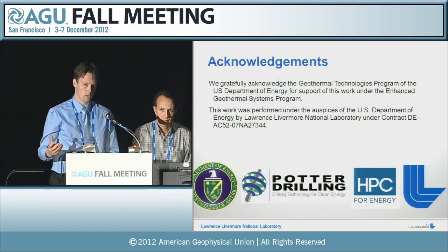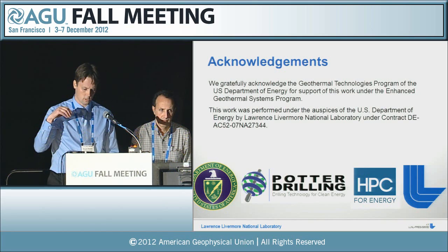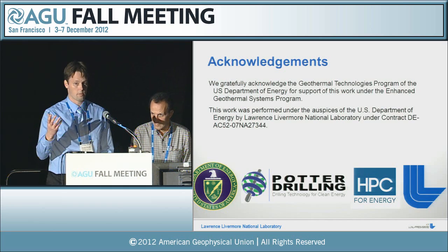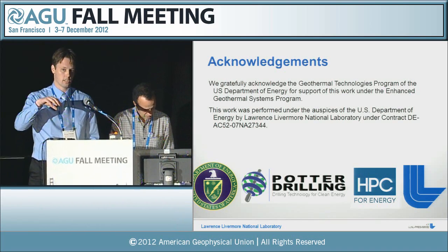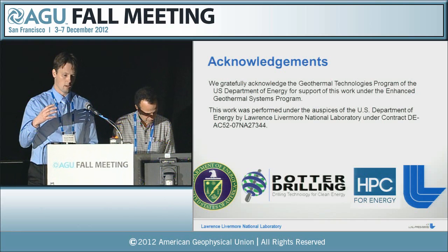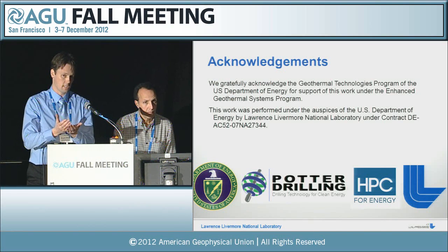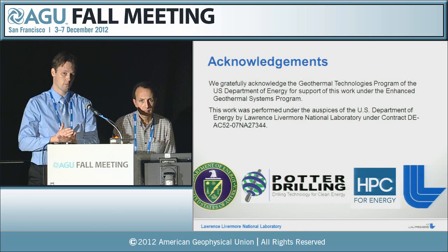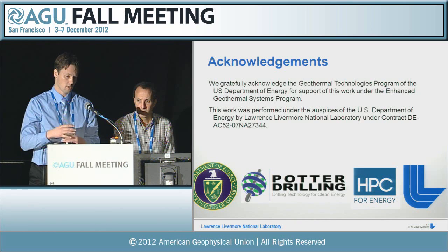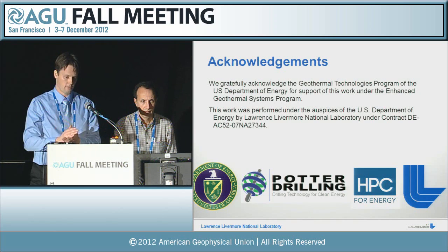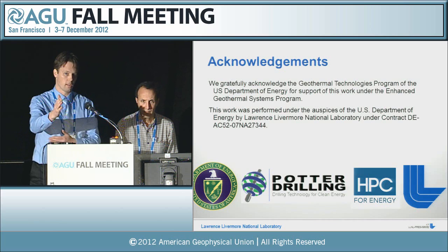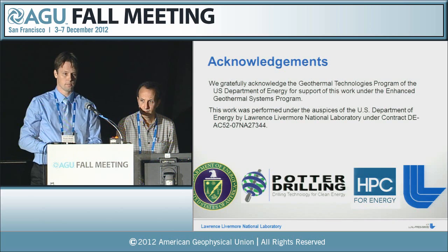The Eulerian model that we use allows us to simulate, so typically what happens in these spallation events is you get fracture initiation at the boundaries between grains. So you need some way to simulate that initiation at those boundaries, but then the fractures propagate within the grains themselves. So the advantage of using this Eulerian model is that we can simulate both of those sorts of modes. It's not just a failure along grain boundaries, but we also can propagate within the grains themselves.